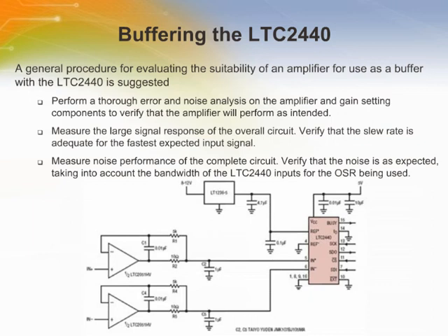The LTC2051 is configured to be able to drive the 1 microfarad capacitors at the inputs of the LTC2440. The 1 microfarad capacitors should be located close to the analog-to-digital converter input pins. Here are 3 items for selecting a suitable amplifier as a buffer.